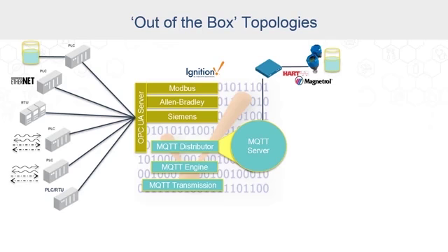So you can see here, I can run these in parallel. I still have my safety critical 4 to 20 milliamp loop, but now I have access to all of the multi-process variables and all of the metrics and all the diagnostics available in smart HART-based sensors. I could decide that the digital signals are fine, and I could migrate that out of being polled in natively MQTT.